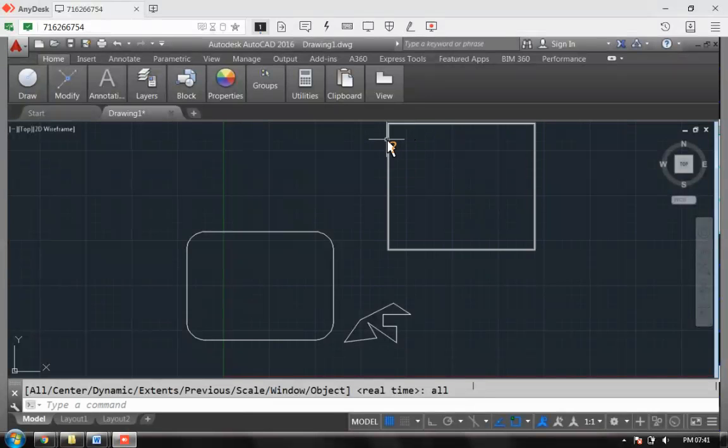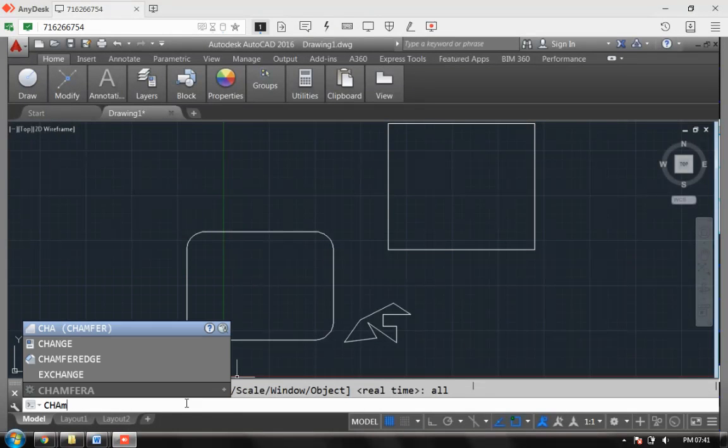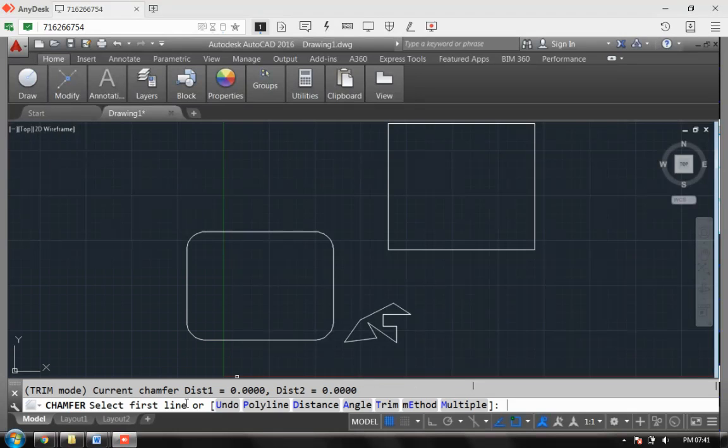Now to chamfer it and cut this way, I have to cut from this point to this point, and this point to this point. In this line, I want to keep this distance starting from this to this, approximately 35, 45. I want to keep this as 5 and this as 2.5 or 2. So I want to make a cross cut here. Again I say chamfer. It is asking what you want to go with: angle or distance. I say distance.